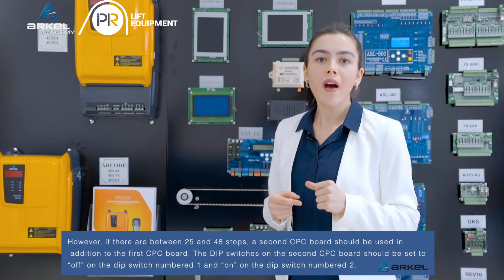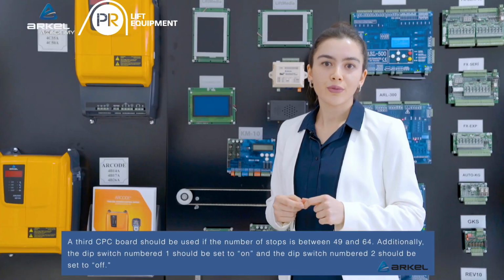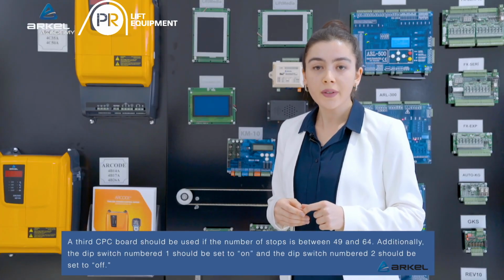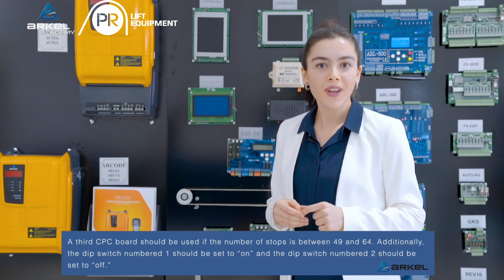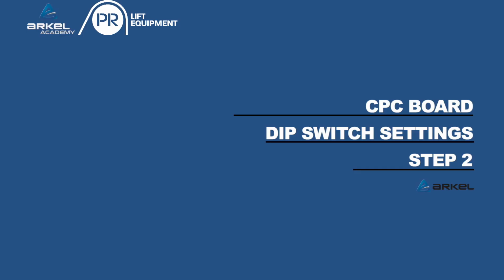The dip switches on the second CPC board should be set to off on the dip switch numbered 1 and on the dip switch numbered 2. A third CPC board should be used if the number of stops is between 49 and 64. Additionally, the dip switch numbered 1 should be set to on and the dip switch numbered 2 should be set to off.